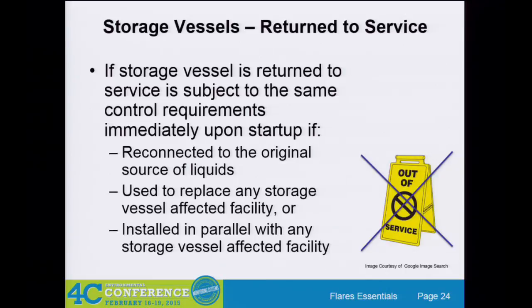Okay, sorry. Storage tanks return to service. If it's returned to service, you have to immediately comply with the control requirements, the 95% emission reduction. So if it's reconnected to the original source of liquids, again, start up with your control device. If it's used to replace any storage vessel or affected facility, so for whatever reason, maybe it's a tank that had a hole in it, that's not typical, but you wanted to replace that tank, the new tank coming in would automatically be an affected facility and start up with controls.